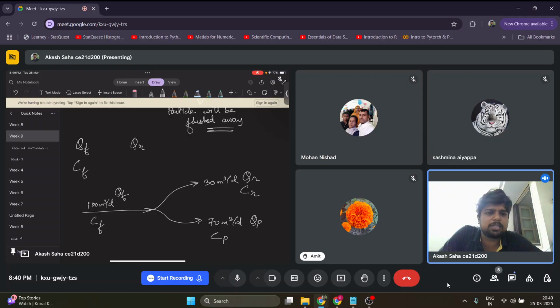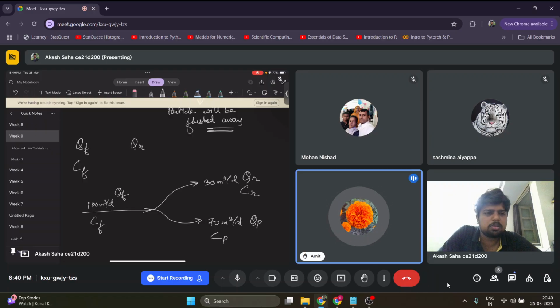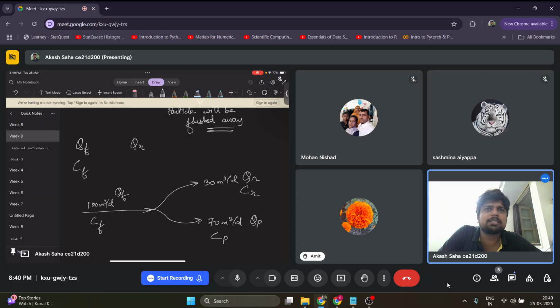It is very difficult because some kind of concentration gradient has to be there. And if you are trying to decrease it by biological action, 70 to 80 can be decreased up to 5 to 10 milligram per liter. It won't be an issue. I know sir, but I think that if there is no organic waste, the microorganisms or bacteria will not be able to sustain, they will not get energy. See, for that reason you may have to store it and then increase the organic loading.